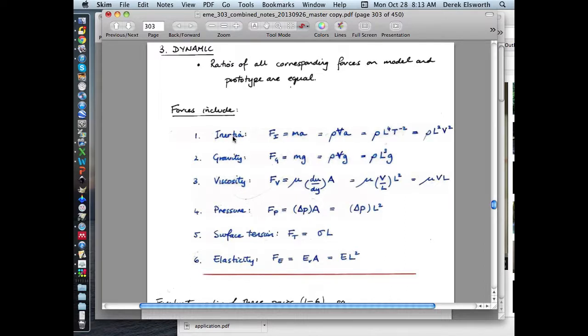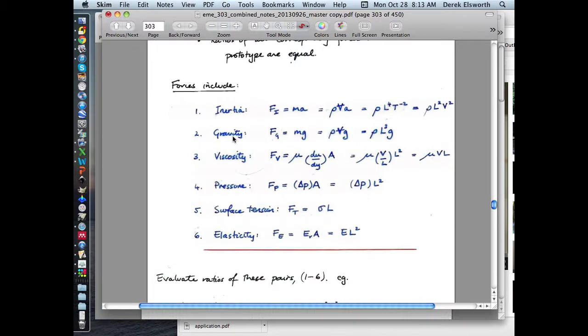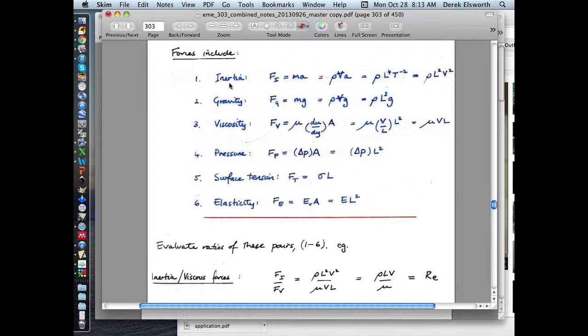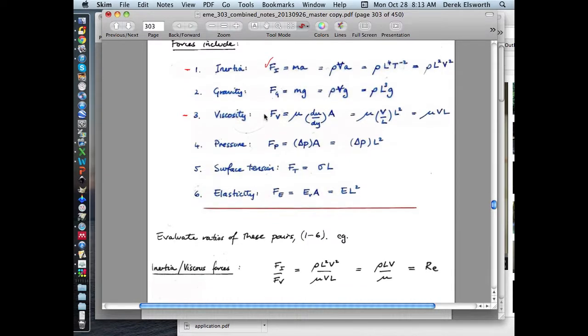We kind of alluded to that in what we just said: if, for instance, you take the values for the inertial force and the viscous force, and look at the ratio of those two in terms of how we defined them here, you end up with the Reynolds number. And so these non-dimensional numbers that we call certain things after their originators are just the ratios of different forces.